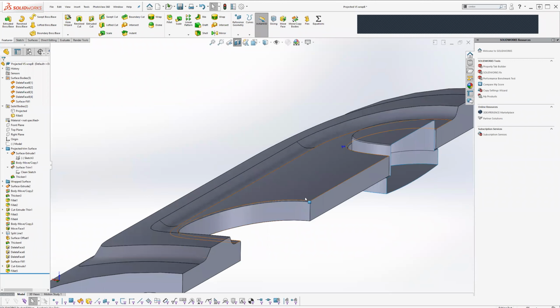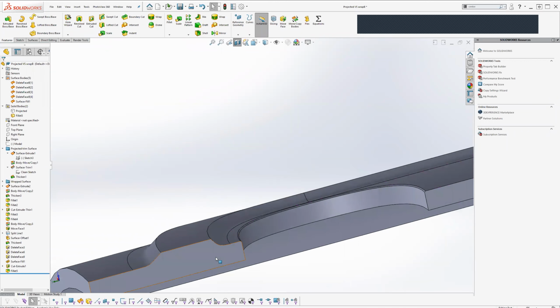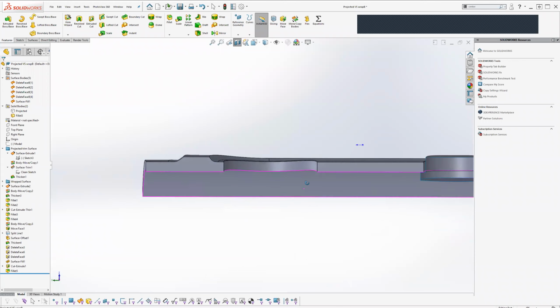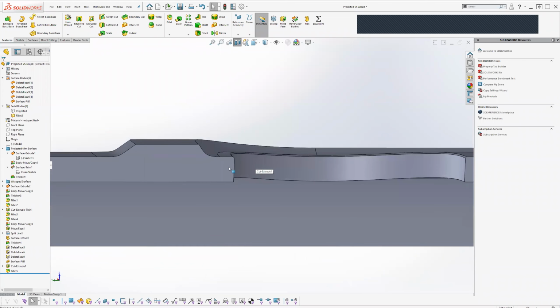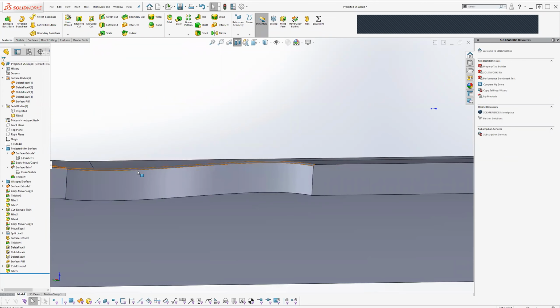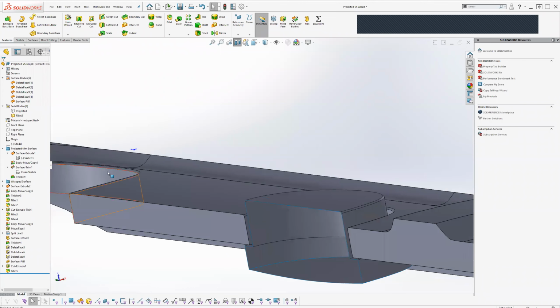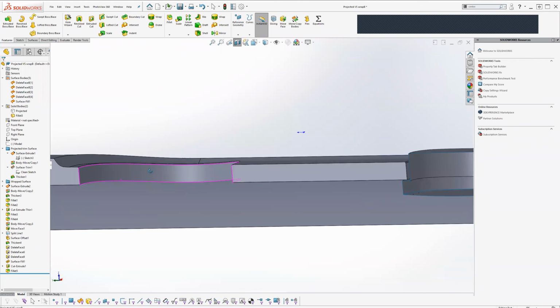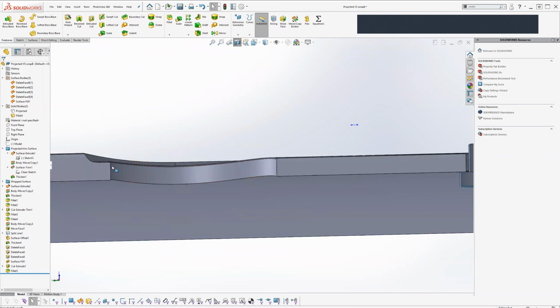So remember, we have a curved surface here. With this curved surface and this knob that you're going to turn, let's say that's the volume button, remember, you have to clear the apex of the surface, which is right in the middle, to the trough area. So that's over here on the side. The knob just has to clear that. And just make sure that the wall thickness going down goes past the lowest part so that you don't have any exposed areas there.